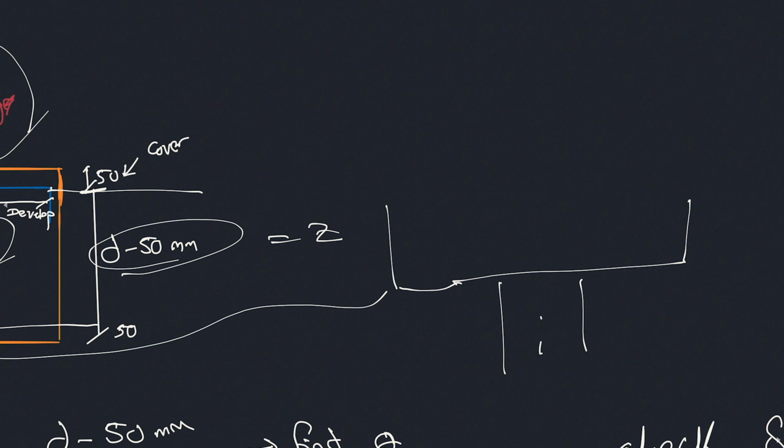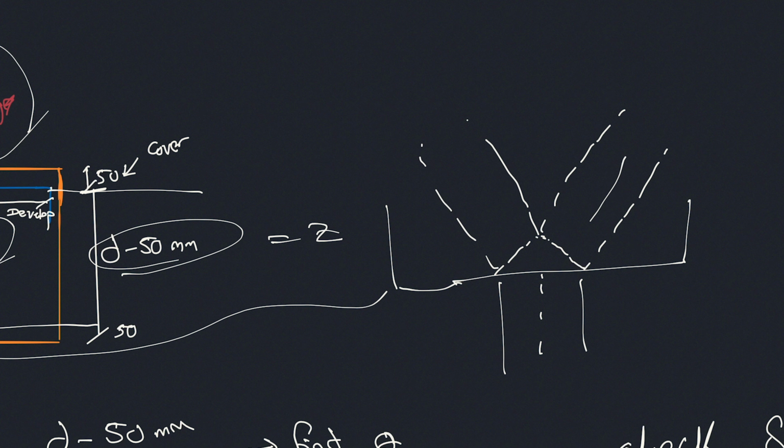And what happens here is that you have the compression force coming in, but first you need to have a face of this node and a face of this node, and you're going to have a stress field, which we are drawing with a dashed line over here, and this stress field needs sufficient distance to get back and align at this point over here.